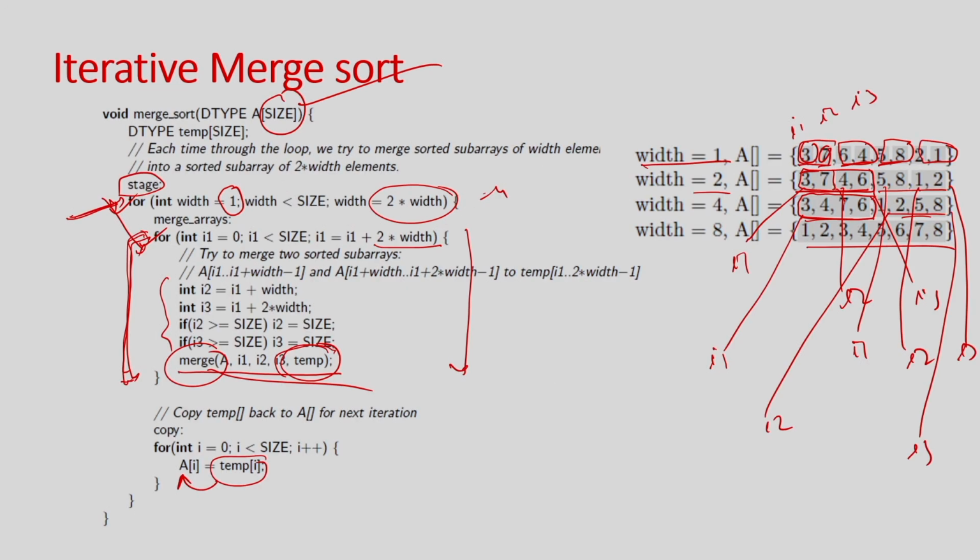And if you look into the code again, since I just talked about 3 levels of loops, you can unroll the innermost loop, the middle loop or the outer loop also, right. In every scenario it will give you a different hardware, or you can think of pipelining the inner loop. You can apply pipeline in every stage, but usually pipeline works better when you apply it to the innermost loop, right. And also you can apply the pipeline at the topmost loop, middle level loop, and so on. You can unroll the innermost and then pipeline the middle one. So there are so many possibilities you can understand here, and you can also partition the arrays. You just think of those things which can give you a performance benefit, right.